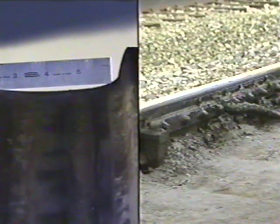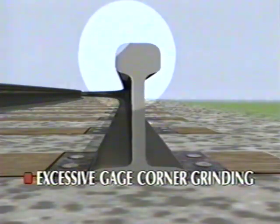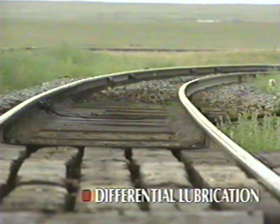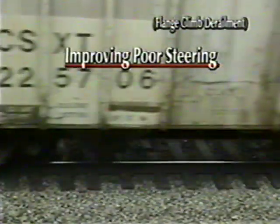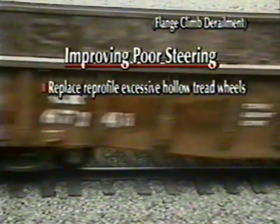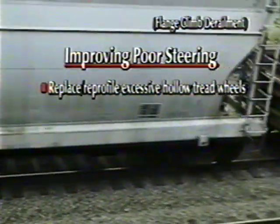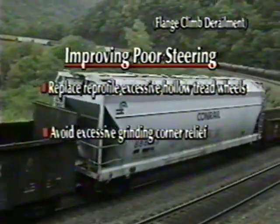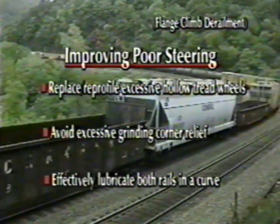Previously, we said that poor steering can resist truck turning. Several factors affect truck steering, including wheel and rail profiles and track lubrication. The conditions which contribute to poor steering include worn wheels that have a hollow tread, excessive rail gauge corner relief from grinding, and the use of differential rail lubrication, where the outer rail in a curve is lubricated while the inner rail is dry. Let's review the efforts that will help reduce poor steering, like maintaining worn wheel sets by replacement or reprofiling when necessary, avoiding rail gauge corner grinding that leaves excessive gauge corner relief, and providing lubrication to both rails in a curve.